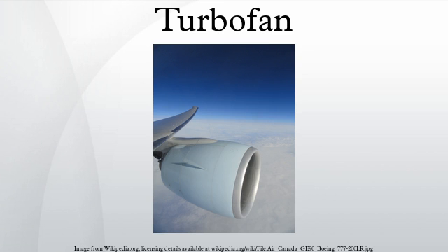Because of the implied low mean jet velocity, a high bypass ratio low specific thrust turbofan has a high thrust lapse rate. Consequently, the engine must be oversized to give sufficient thrust during climb and cruise at high flight speeds. Because of the high thrust lapse rate, the static thrust is relatively high. This enables heavily laden, wide-body aircraft to accelerate quickly during takeoff and consequently lift off within a reasonable runway length.